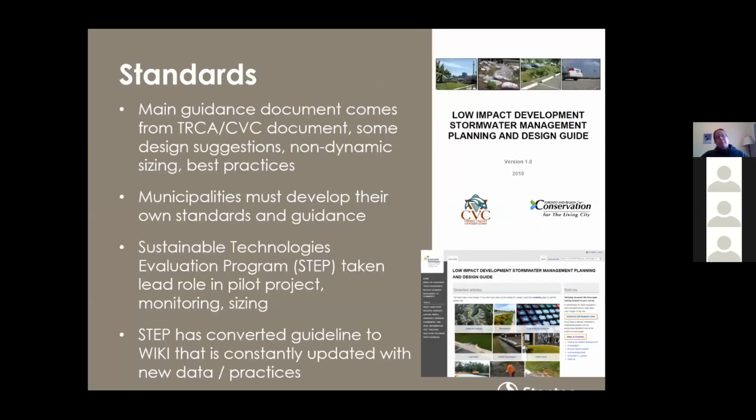So we do have some guidance documents in Ontario. In some ways, Ontario went the exact opposite way of Vancouver. We don't have the guidance and we don't have the provincial documents, but we're putting them into the ground all over the place. So our main guidance document comes from the Toronto Region Conservation Authority and the Credit Valley Conservation. It has some sizing and design suggestions. Most of the sizing is non-dynamic sizing, so it doesn't account for evapotranspiration or infiltration over time, as well as some best practices in terms of maximum slopes, depths of soils, and things like that.